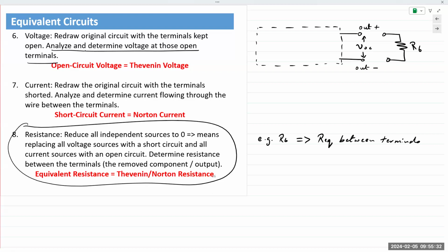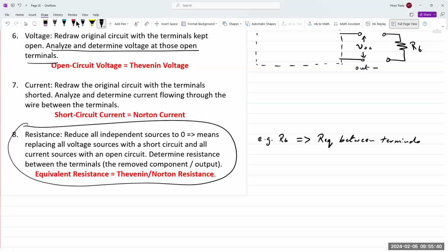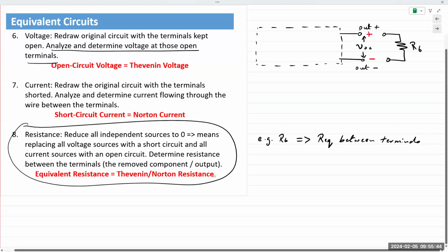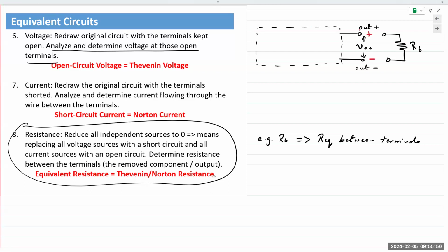So open circuit, you find the voltage between those pair of terminals with a positive up top. Okay, the reference polarity is always plus up top and minus at the bottom, depending on the circuit. Now your answer could turn out plus or minus, that doesn't matter. But when you're analyzing the circuit, you always find VOC with a plus on top.